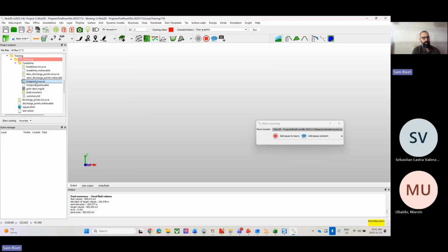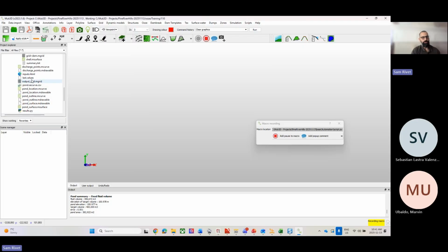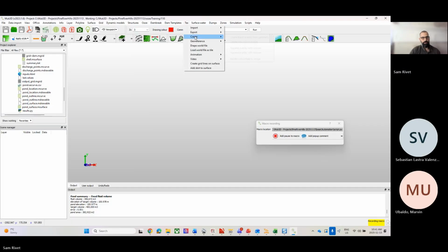I can just open that up. That'll make it look nice. But I need to edit that satellite photo to show that there's now a dam structure and tailings placed. So I have line work relating to the footprint of the dam and to the footprint of the tailings. I'm going to use those to modify the satellite image. So I'm going to go to the template, create, pen overlay with colors. This function is, once again, going to edit satellite imagery to now represent that there's a dam and some tailings. And I'm going to do that in every time step so we can see that evolution.